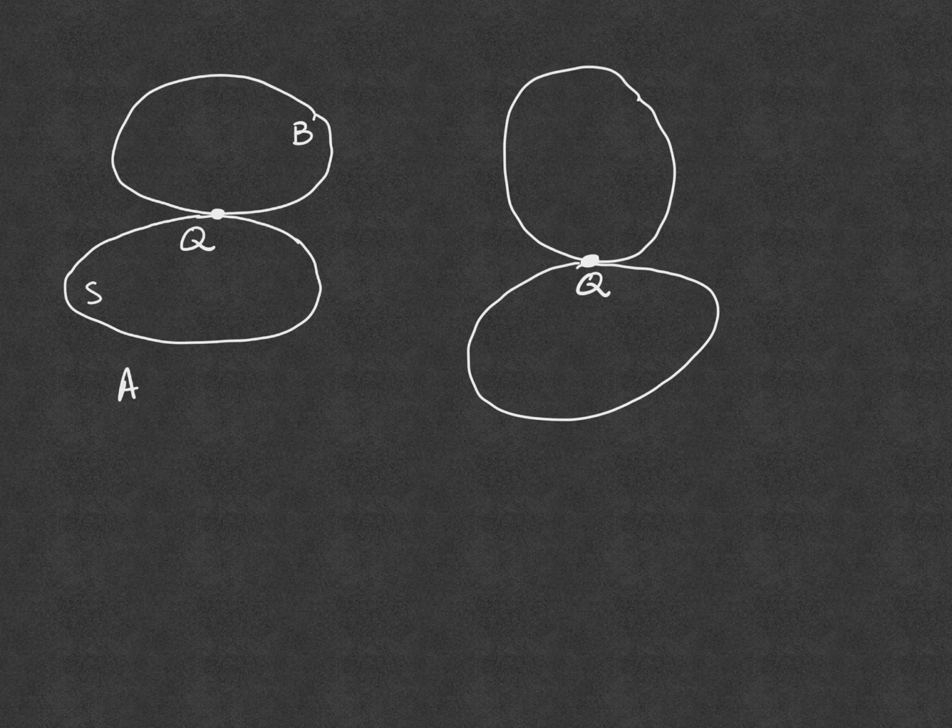So you can think of this as at t equals t1, and you can consider this to be at t equals t2, and the point of contact has changed. So it's an instantaneous point of contact in that it only applies at that particular instant. So at time t equals t1, the point Q that's in contact between the two bodies is the point that's defined at that instant to be in contact, and that point changes as time evolves. That's a confusing concept, and it's understandably confusing, but the point of contact does change as the two bodies move relative to one another.